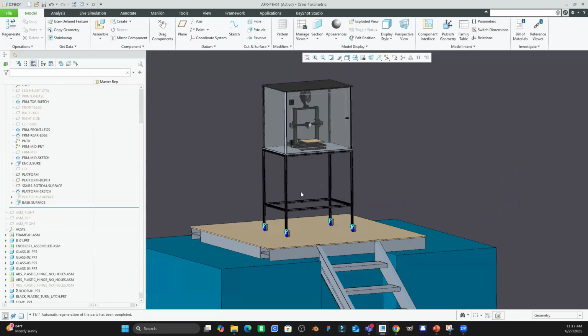I would say for the design, the most important thing is that we always modify the models, because you cannot make it once, right? So that makes it much easier to modify the file and make everything correct. Based on my experience, the biggest fear for the engineer and designer is that when you modify the file, you mix something up. That will cause some interference that you never find. Once it goes into tooling, it's too late to find it out.